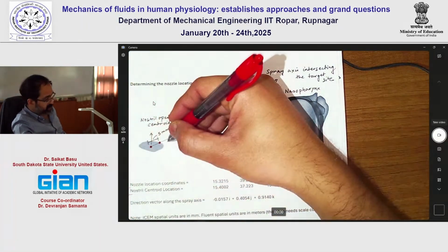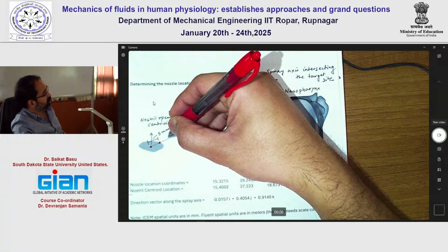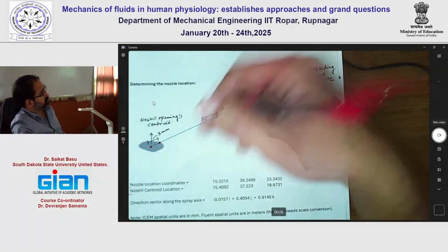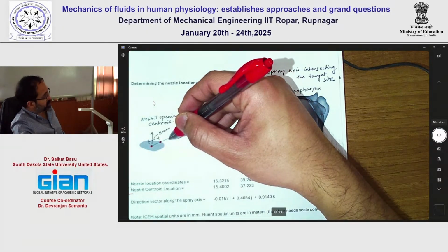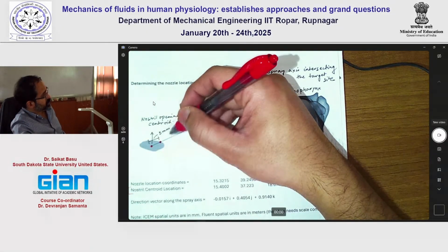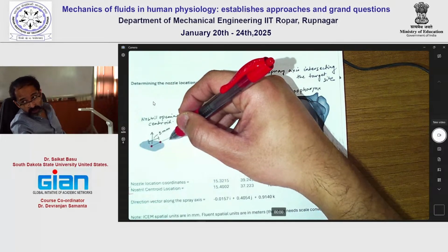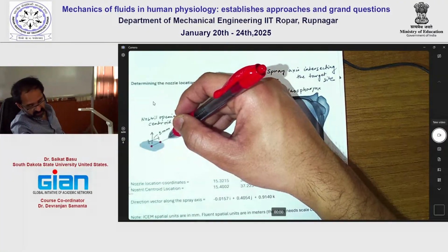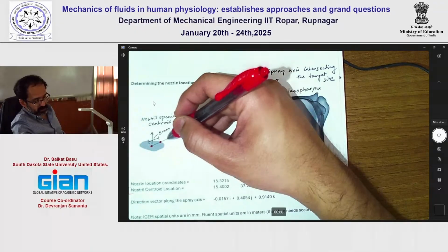Now, if you take a point which is further in, say 10 millimeters into the airspace, obviously you will get better drug delivery because you are starting the particulates further into the airspace. Question is how realistic that is. How far deep you can put the spray nozzle inside your nose. There is the discomfort issue as well. There have been works in literature where they have taken deeper locations for the spray nozzle, but just so that you know, this is the standard protocol.